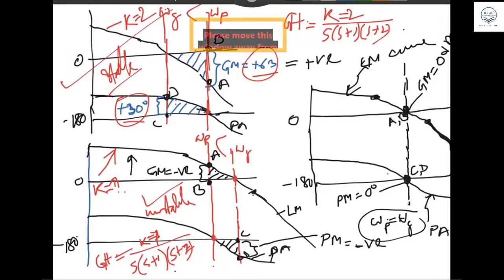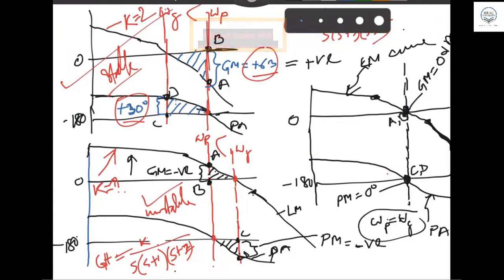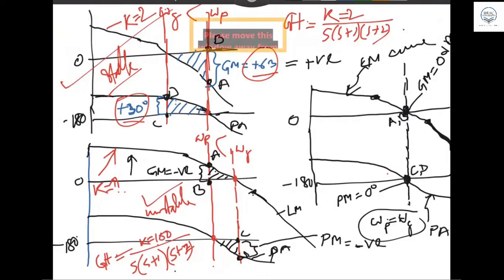Sumaya, last time you did the Nyquist stability criterion. Was it stable or unstable? We considered the same example. What was the K value there? In the Nyquist, what K value did we consider? 100, sir. If we consider 100, which is more than 6, the system gives you unstable. Remember, -1 is inside, meaning N equal to 2, 2 poles on the right half plane, system unstable. Because 100 is more than 6.